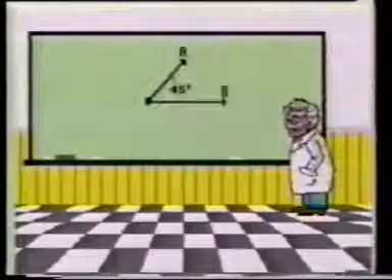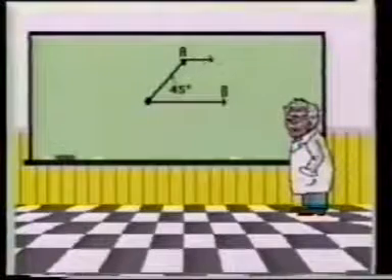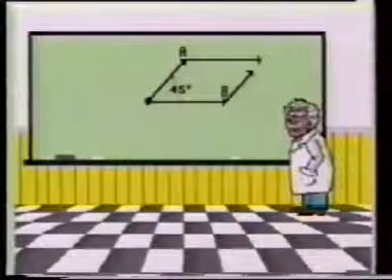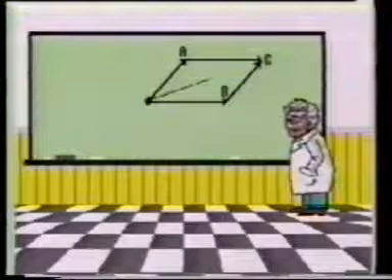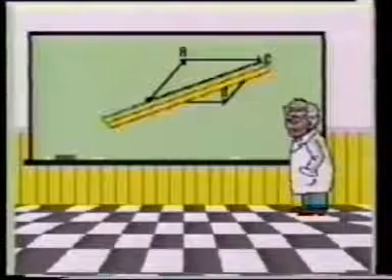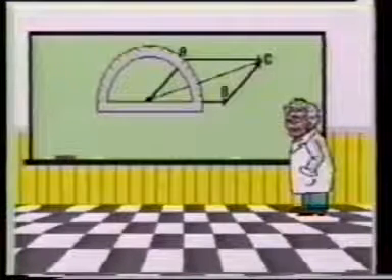Before proceeding into the next part of the program, let's review the information just discussed. As you have seen, AC voltages are not always in phase. Therefore, to calculate the total voltage of two out-of-phase signals, you must use the parallelogram method of vectoring.